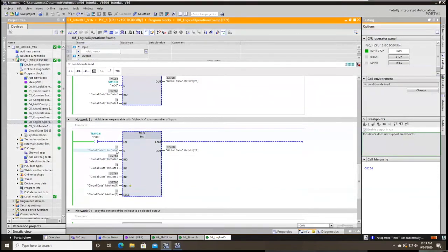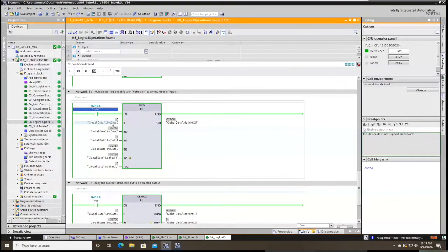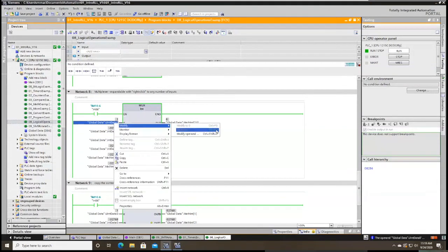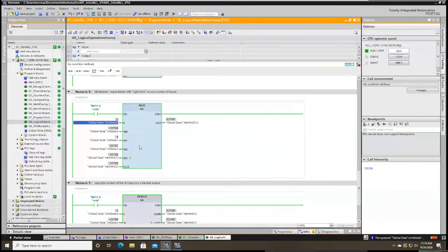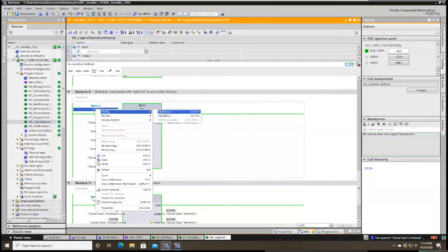So right now it's set for 0. A multiplexer, basically, if this were to go true, depending on the value of K, it would move said value to the output. So since it's looking at input 0, which is 0 right here, it moved that to the output. Whereas if I modify this to a 1, it's now moving 6 because 1 is input 1. So that's what a multiplexer does. It moves a defined set of inputs to the set output based on the value of K.